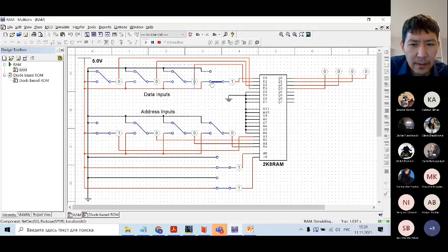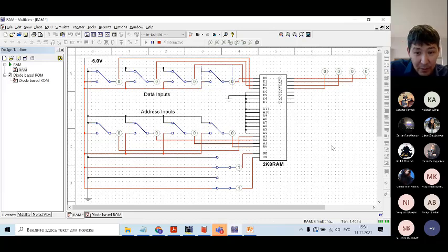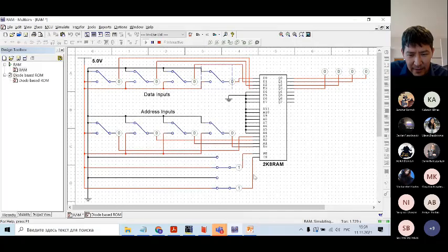So teacher, when we are reading some information, we need to put chip select and write enable high, yes? Right, enable and the chip select, yes, you need to put high. Yes, high. Because we don't have this bubble, actually you can connect an inverter here, and you can use this truth table if you add two inverters here. Okay, so guys, let me restart this one.